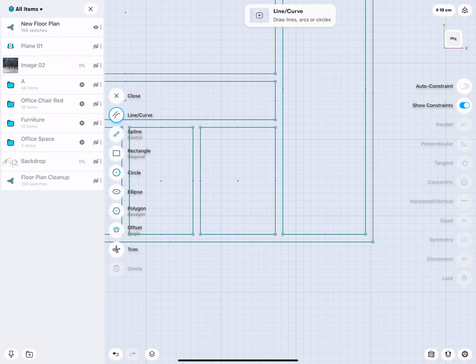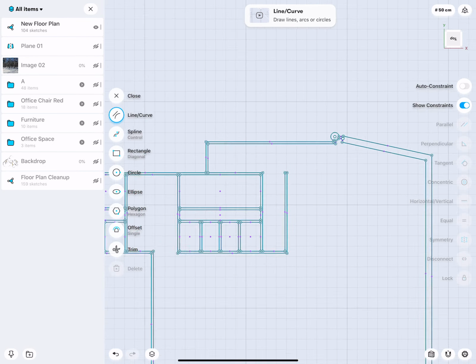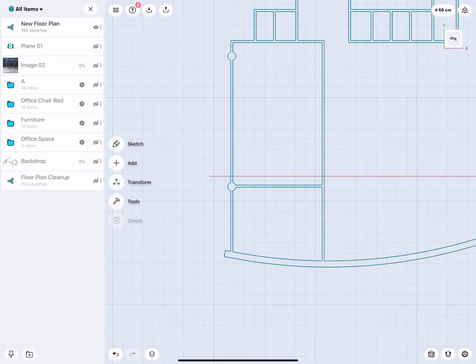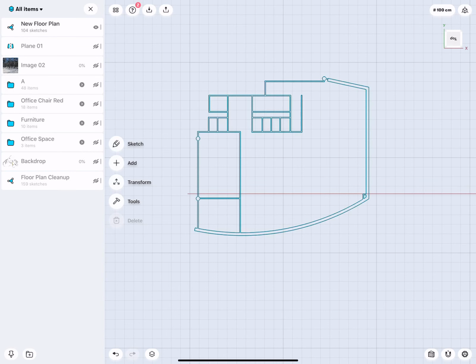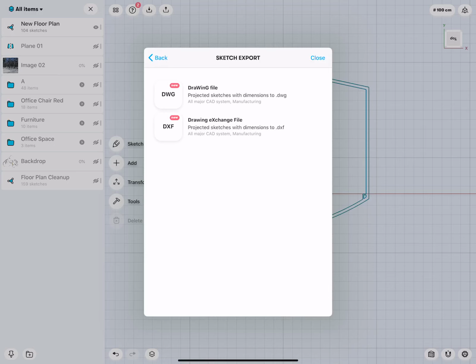You see this is now a new sketch that was created based on the modeled geometry. So that's actually very easy. You can just push and pull. Let's say you would like to do remodeling. The remodelings will not be part of the original imported DWG. And then from this remodeled geometry, we simply create a new DWG. And then that we can export as a new sketch. You select your type of flavor, DWG or DXF.